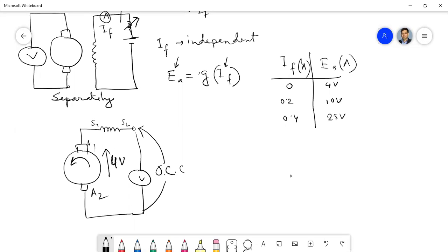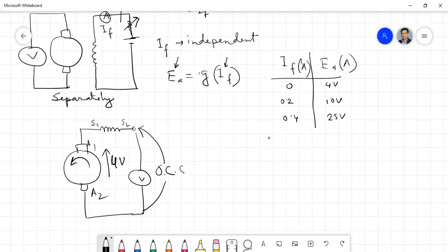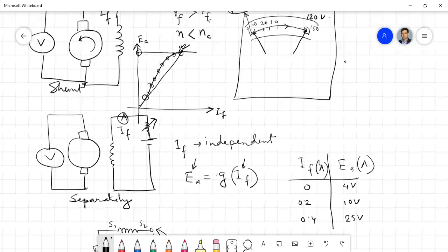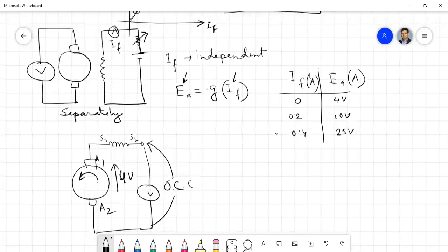So you can take this perfectly open circuited, because if your 10 kilo ohm is there, how much current will flow? Only some leakage current may flow. Okay, sir. Some current should flow through the voltmeter, otherwise the voltmeter couldn't measure any voltage, isn't it?